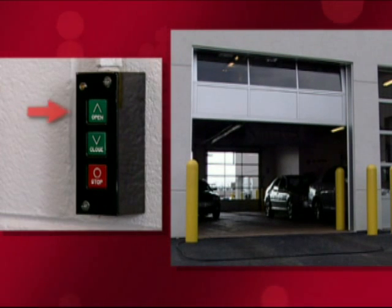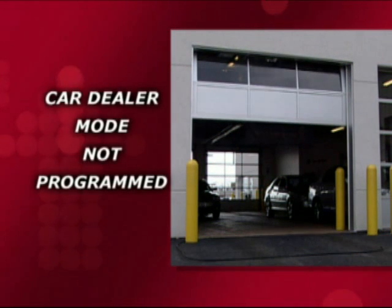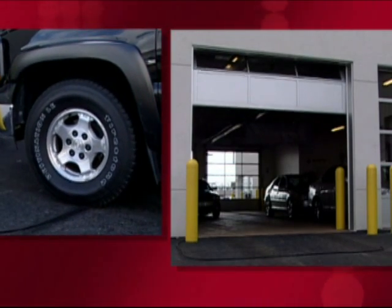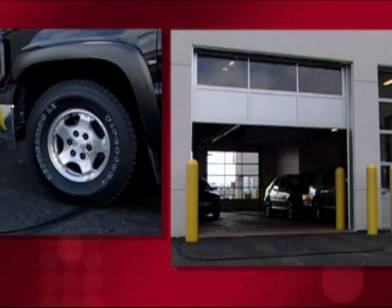The door will open fully when the open button on the 3-button control station is pushed. If the car dealer mode has not been programmed when the door is at mid-stop, activation from a treadle or loop detector will fully open the door. If the door is closing, activation will fully reopen the door.